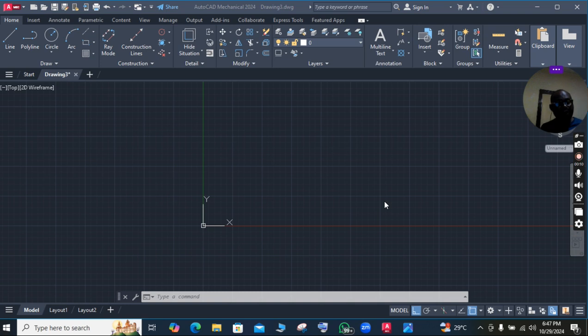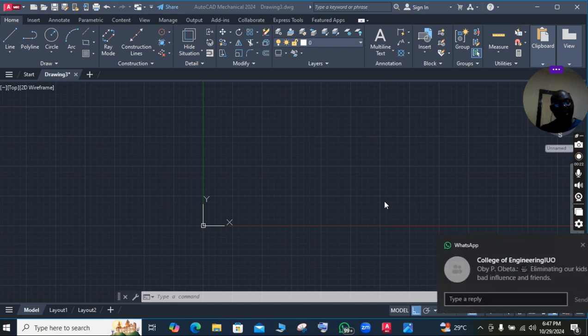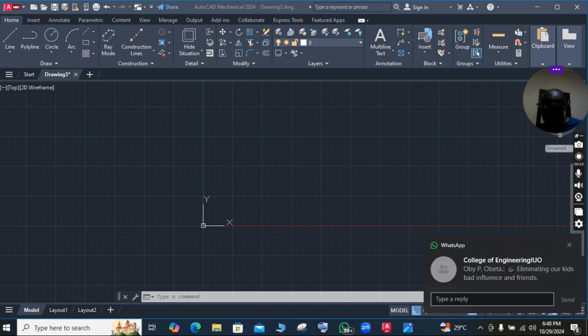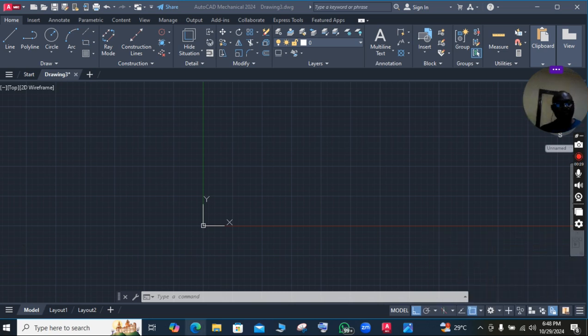We shall be looking at extruding along paths, extruding with taper and lofting. Specifically, we'll be looking at extruding to create 3D objects. So we'll look further at the extrude command, how it can be used to create a 3D solid from a closed 2D shape.